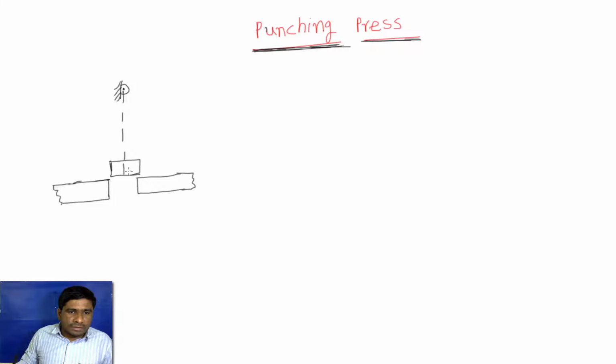So for example, if I consider a general two-stroke reciprocating engine, so this is my punch that has been attached to the reciprocating engine, and this is rotating like this in this direction, so that this punch, this is a slider, actually. This is a slider crank mechanism, simple slider crank mechanism, and this slider is replaced by a punch, and this is my plate where I need to get a punch.